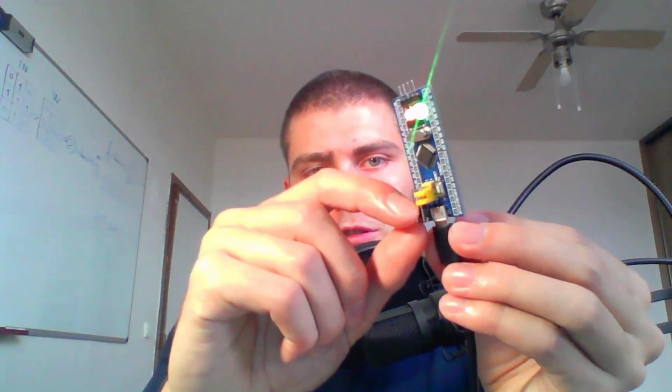This is a simple application 2, but the point is that the microcontroller is currently running application 2, and the bootloader was running only at the very beginning after the reset. After it jumps out of its boundaries, it runs a totally different application. This is the point of this example, that the bootloader can jump to multiple different applications, as many as you want.